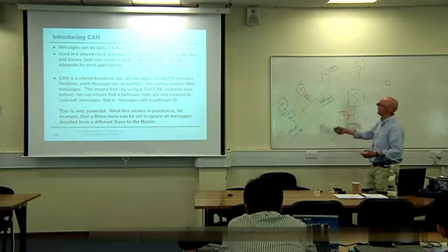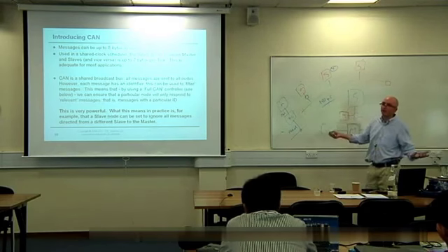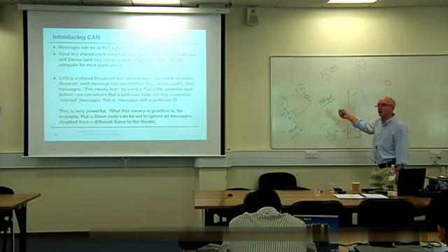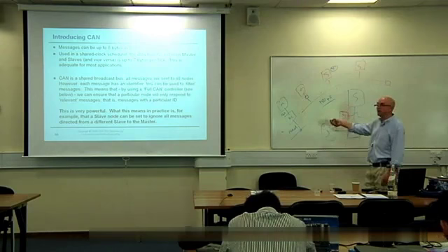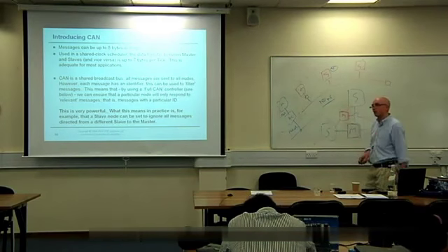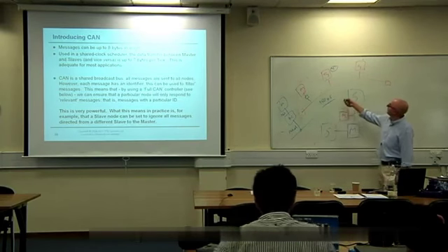So essentially, he sends a tick message on the bus. He knows exactly how long it will take. It can be no closer than 300 microseconds later, because of the message lengths, that the message will be back. So he knows exactly when he should be looking back in there to check whether he's had a reply. Doesn't need an interrupt here. Maybe this case is more straightforward.